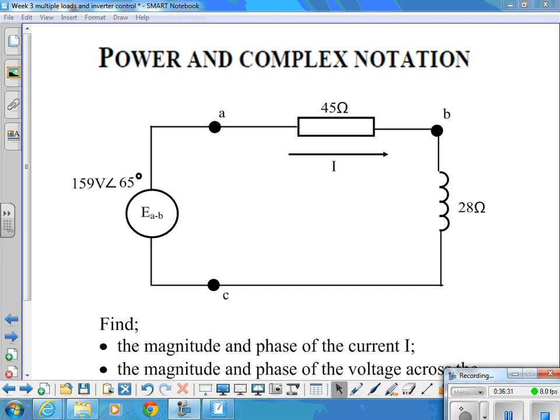Don't forget, we haven't covered three-phase systems yet, but they consist of three voltages that are all 120 degrees out of phase with each other. So you'll have one phase at 0 degrees reference, but a different phase could have an angle of 120 degrees associated with it. So it's not unrealistic for the voltage to have an angle. It's all about what we choose to be the component that's got 0 angle.